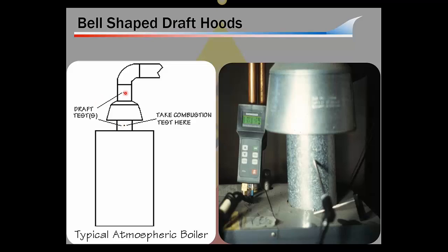I've seen guys try to test them up here because they just simply didn't understand what the function of this thing was. It's just another type of draft hood that allows outside air to mix with the flue to help it vent and stay dry. Okay? Draft test, of course, we would do above it. Combustion we do below.